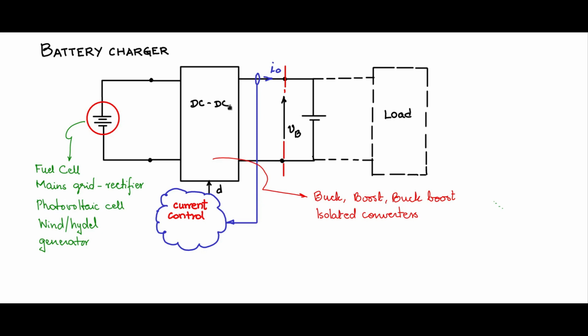In the case of the buck converter that I will be discussing, the inductor current control and the output current control will become the same. Some of the advantages of current control is that there is inherent overcurrent protection. So cycle by cycle instantaneous overcurrent protection can be achieved with current control.